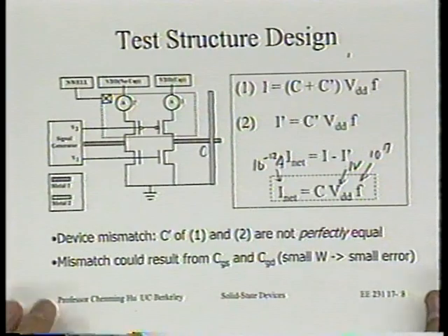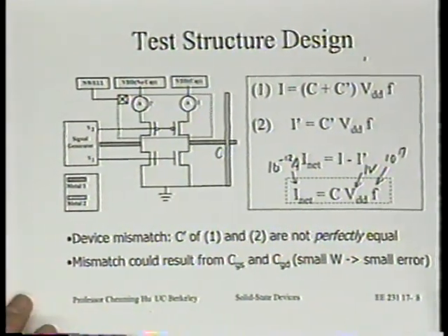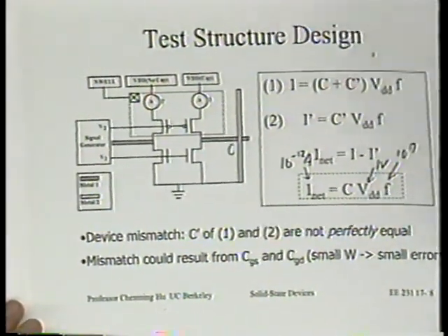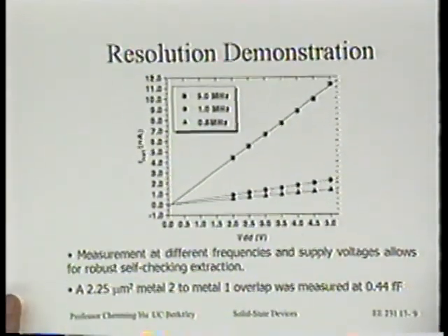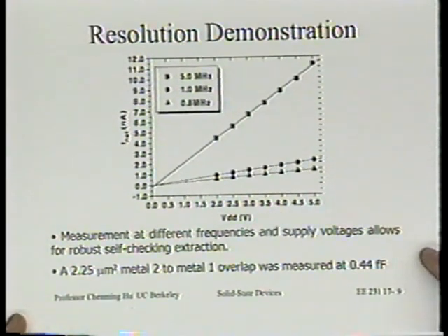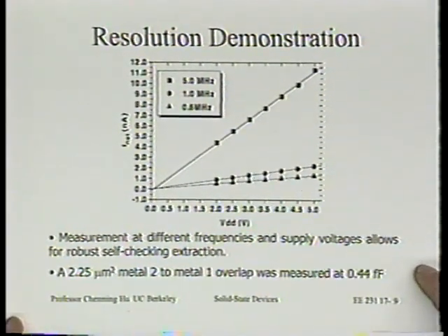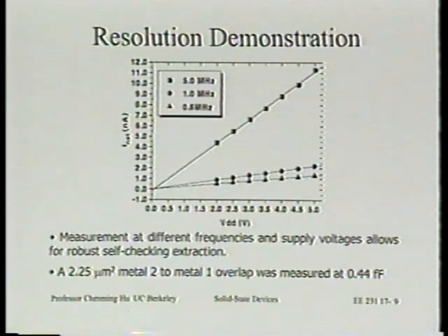When the intercontact capacitance is only 1/100th of a small transistor's, say, junction capacitance or overlap capacitance, you better be satisfied with that. So this turns out to be a very good technique, and the design community has proposed to use this as a standard in the industry to calibrate the design tools, because we can have capacitance models and capacitance simulators, but finally we still need experimental verification so that we know whose model is right, who's better, and whether the model can be counted on to give us good design accuracy.